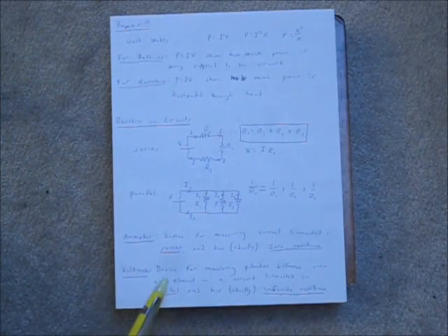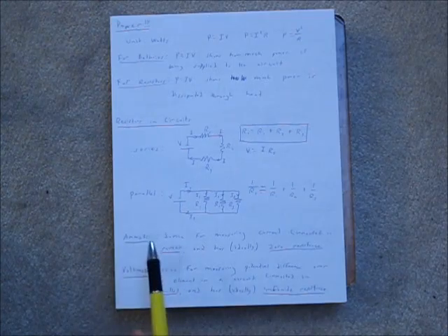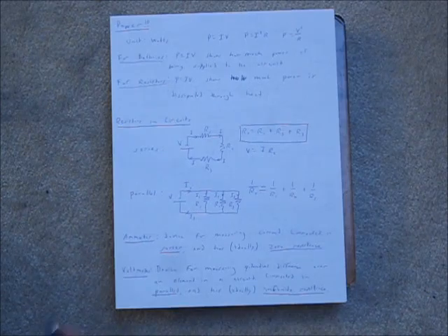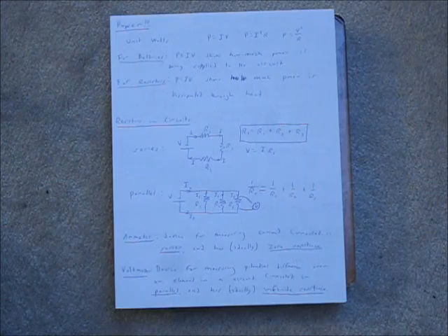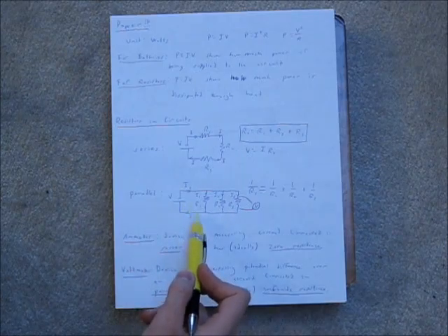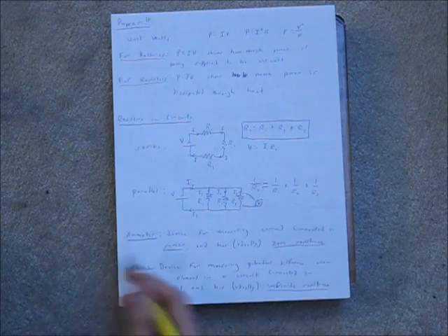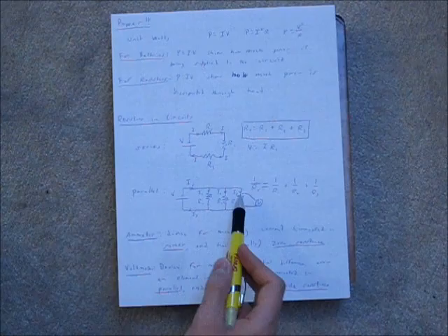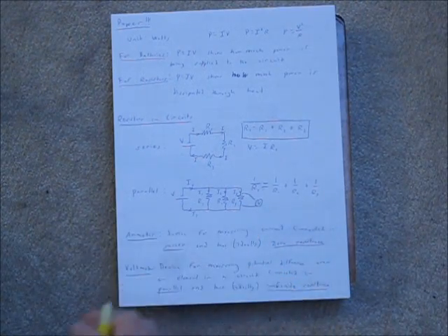So an ammeter is a device used to measure current, and you would put it in series, and it would ideally have zero resistance. A voltmeter would be connected in parallel, like this, and ideally it would have infinite resistance. This all makes sense because an ammeter in series should have a minimal effect on the circuit, and here you wouldn't want some of the current to go into the voltmeter as if it were another parallel branch. So you would want as much resistance here as possible.